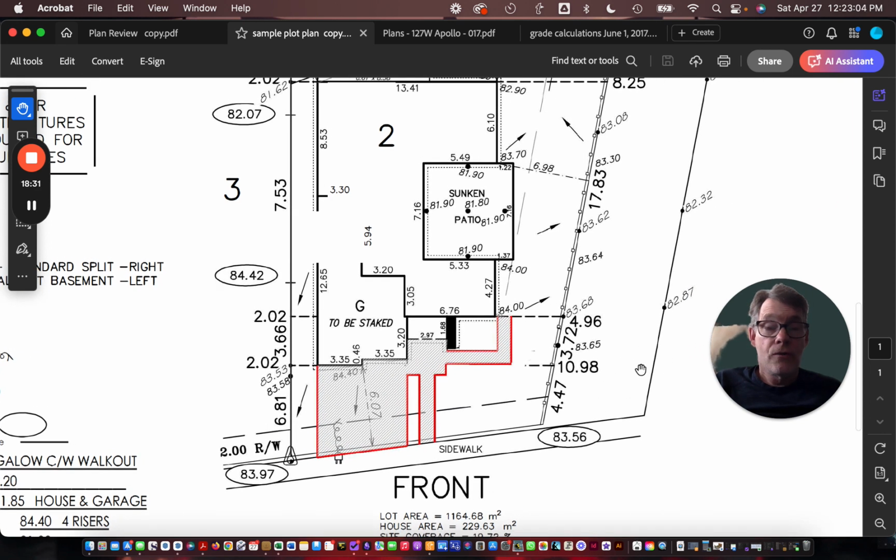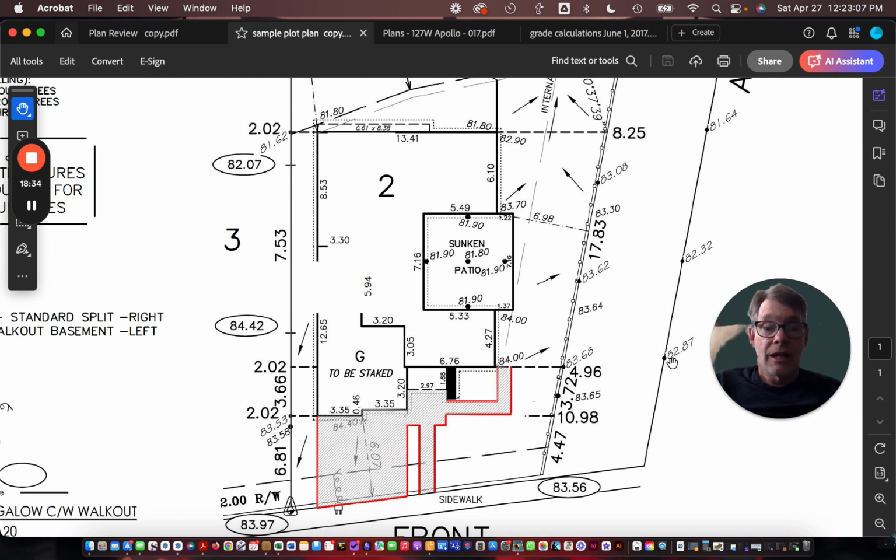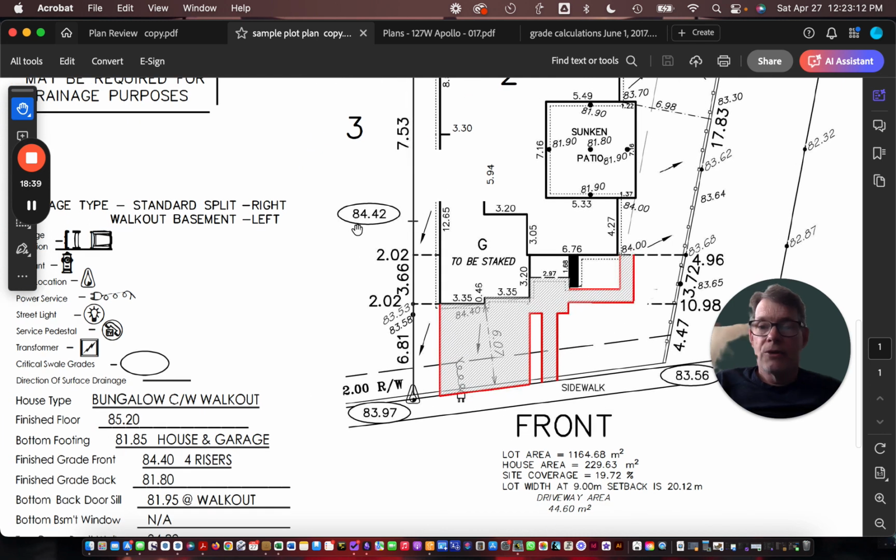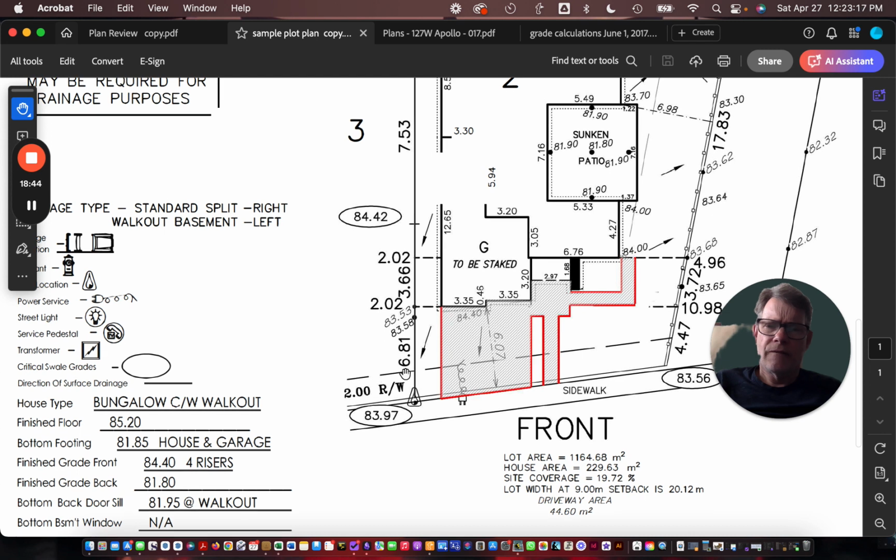We know that we have actually a walkway next to us, and it's clear that walkway is lower than we are. Beauty, that's great. And there's a neighboring lot beside us. We don't know a lot about that lot from this scenario, but we do see that we are draining that way towards that lot. He's probably draining that way, and so there's probably what's called a swale, which is a channel. It can be very subtle, can be even hard to see with the naked eye, but there's a channel there, and it's allowing water to flow, in this case out towards the street. So I think we're cool here, and we should be.